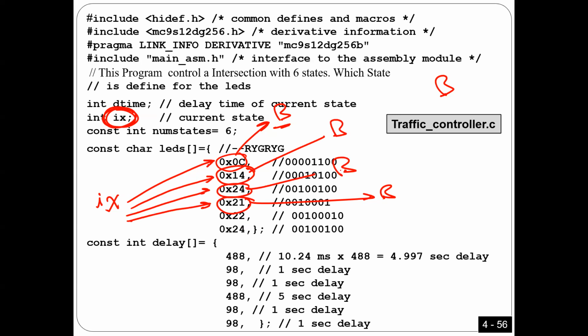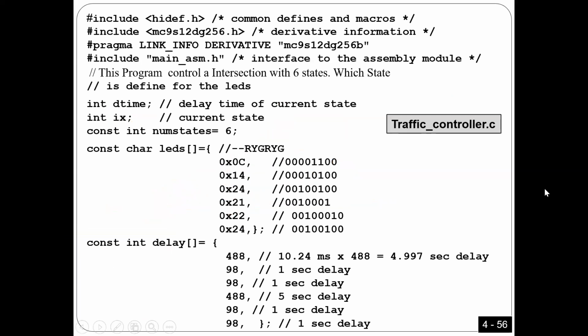So the question is how I can control the time here. How can I control the time? I'm gonna tell you, it's also very easy. The way you are gonna do it, guys, is using the number of interrupts. What do you mean? Look here, guys, the idea is very simple, very interesting. If we create an interrupt every 10 milliseconds, so we have an interrupt every 10 milliseconds.